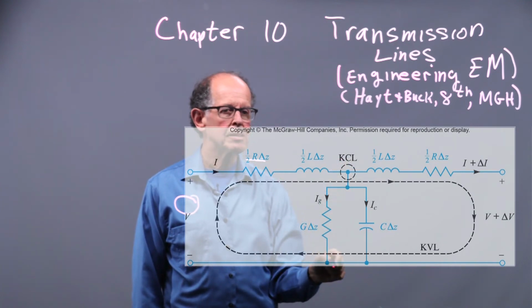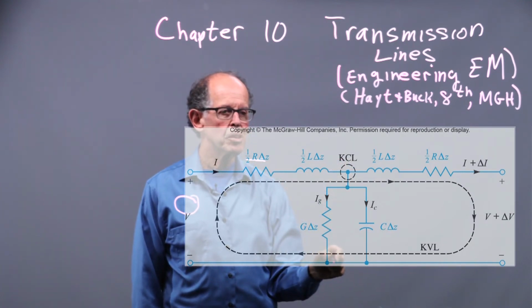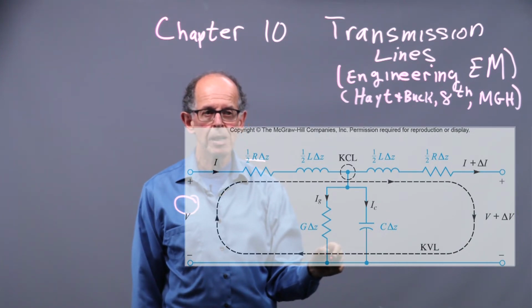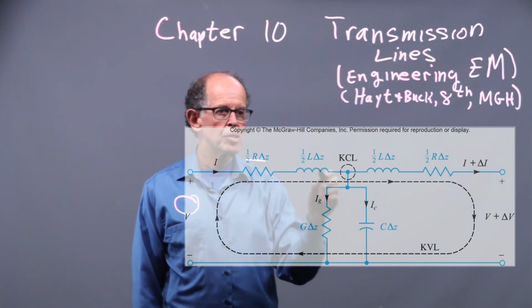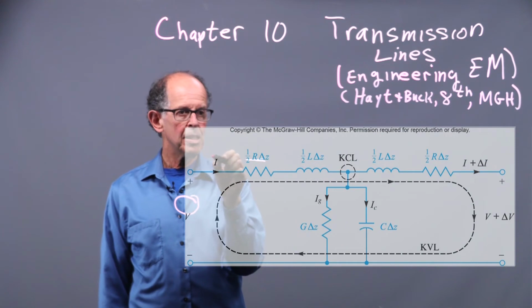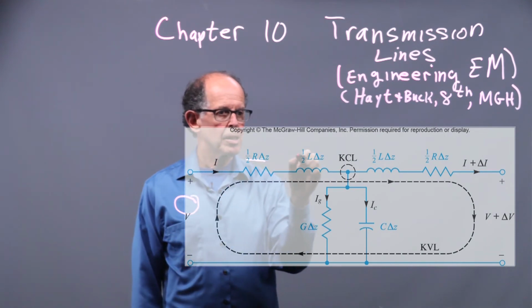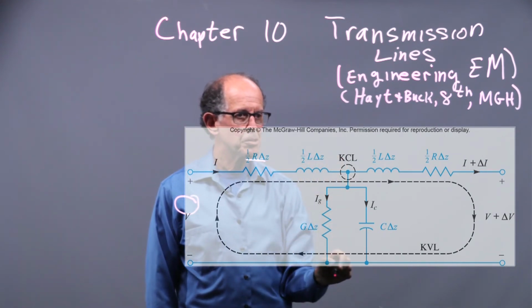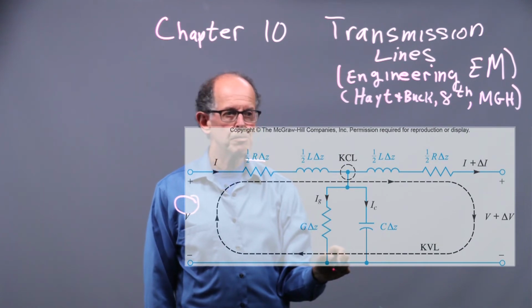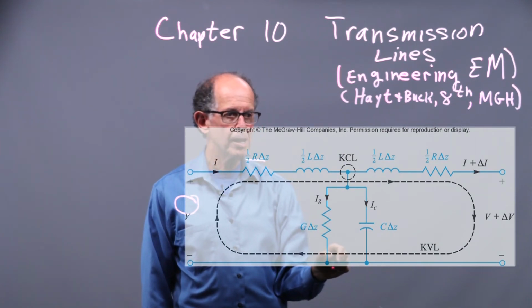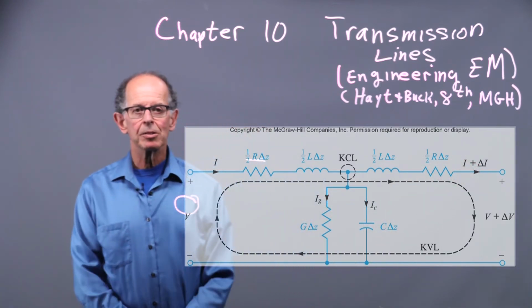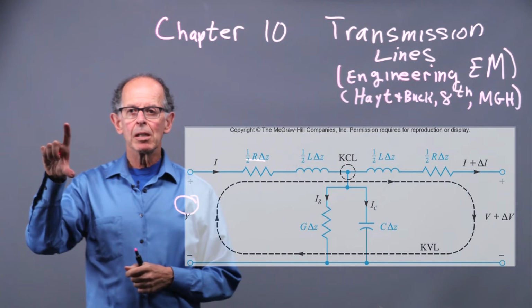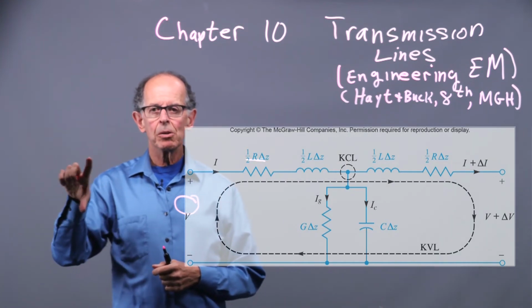across the line. And that's something that we don't normally think of in a circuit. This is the wave part. This is the Maxwell equation modeling in terms of this circuit element. And since the current I over here is getting diverted at this node across, that's a model for the coupling between the top and bottom of the line, plus minus, the current at the other end is I plus delta I. So at one end of the line, we have a V across the line.